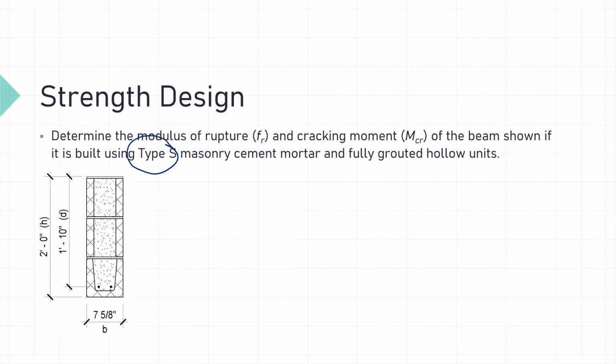In Michigan, we use a lot of masonry cement mortars because we are not in a seismic state where we have a lot of seismic restrictions, and most of our contractors are used to using masonry cement mortars. I advocate for using masonry cement mortars, especially in veneers in Michigan, because they're easier to clean. But we can get into that topic a whole other time. So we have everything we need to know here.